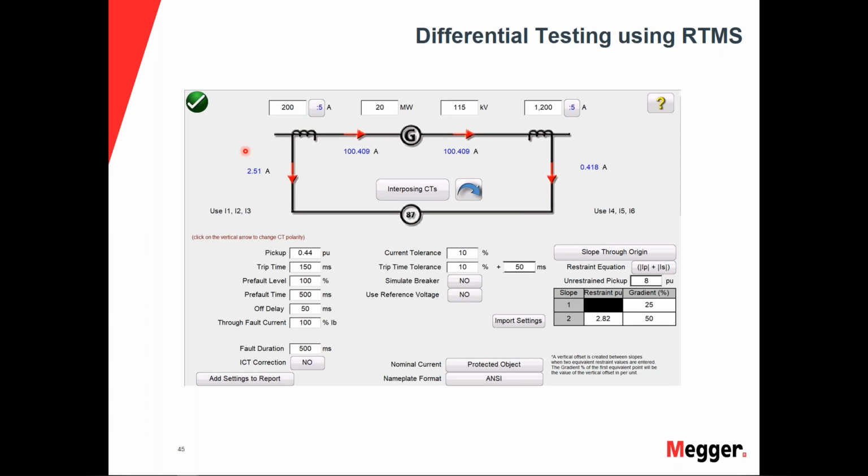We have a few drop-down lists for different manufacturers, but most of this information gets put in from the settings, so you shouldn't have to go hunt it down. You should be able to get everything you need to fill this sheet out from the settings by pulling them from the relay, or if you have a 3-phase electromechanical relay, you can pull those settings from that relay itself.